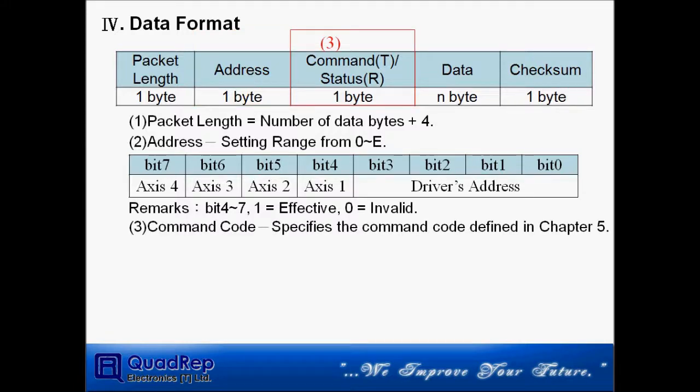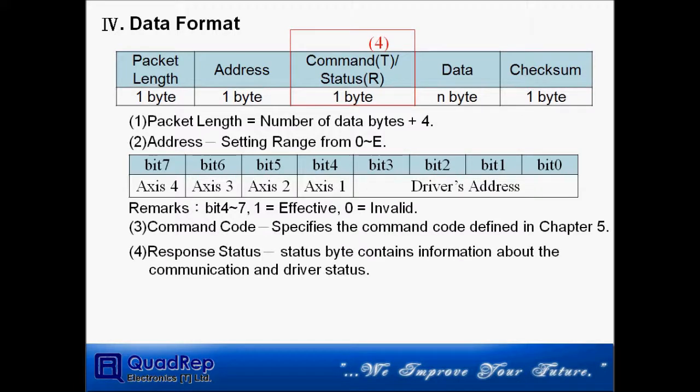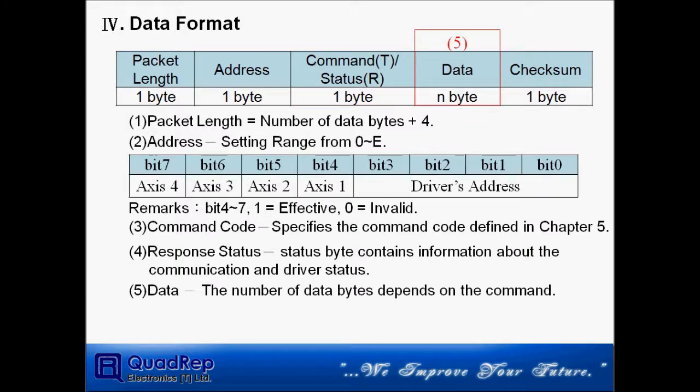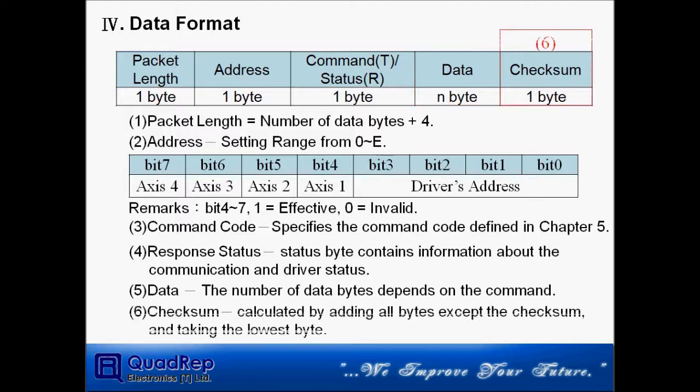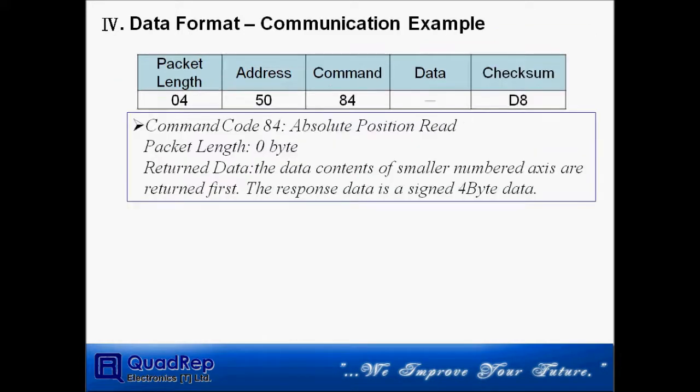Specify the command code defined in the instruction manual. The status byte contains information about the communication and driver status. The number of data bytes depends on the command. Checksum is calculated by adding all bytes except the checksum and taking the lowest byte.